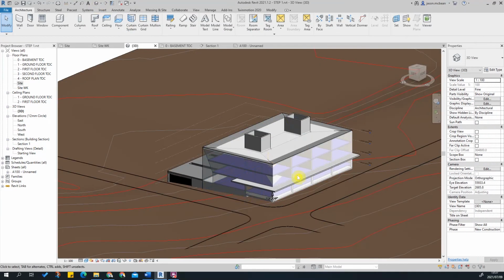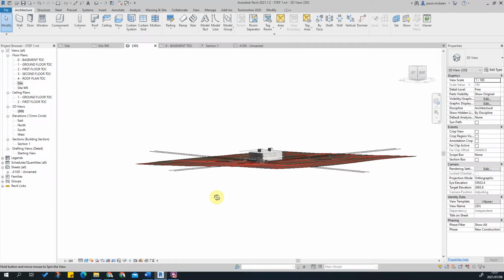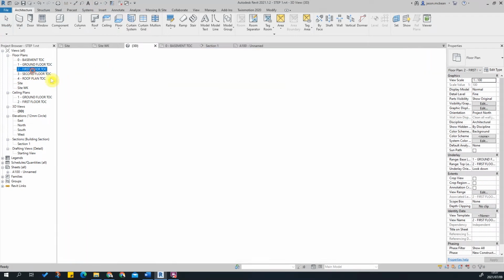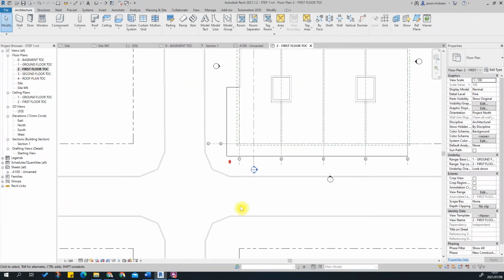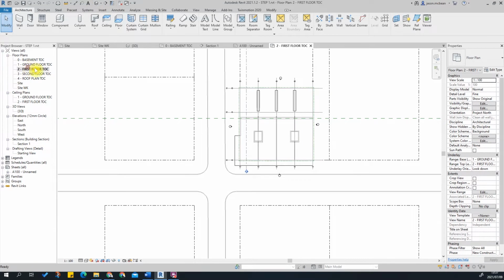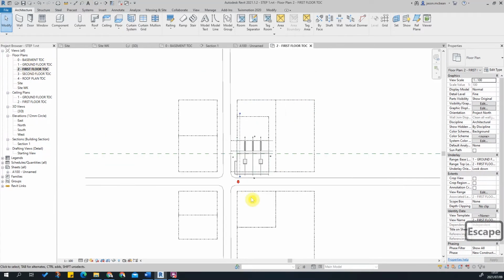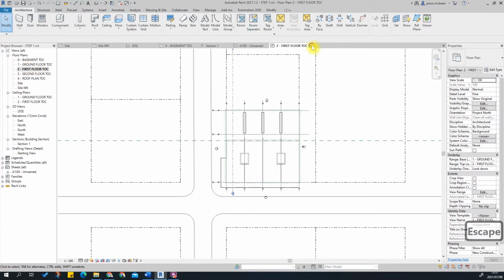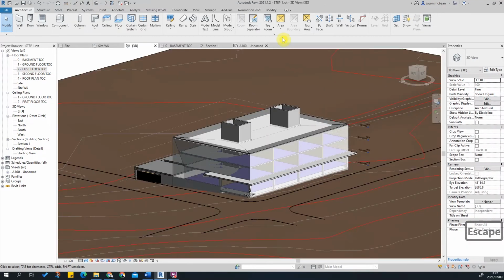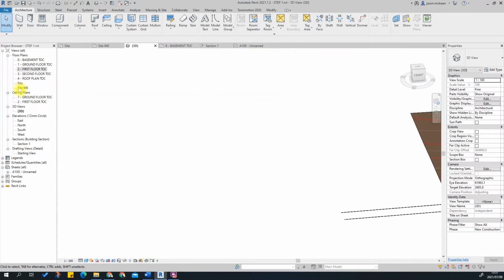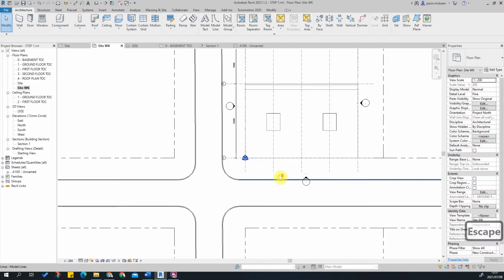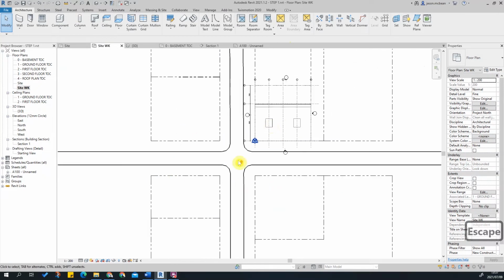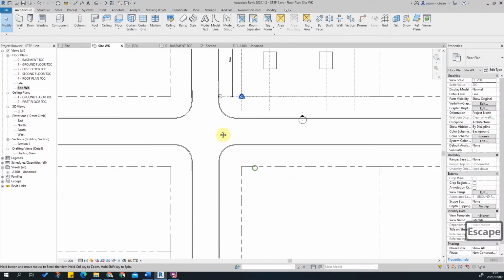Just remember, these are model lines, so they are visible in 3D. You want this because it means if you go to other views, you can start seeing the road network behind, if you want. Okay, so that's why we would want to do this. There are situations where we'll use detailed line work instead of model line work. But we've got our road network established.